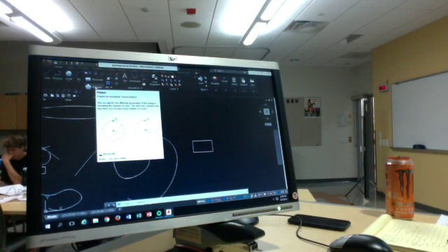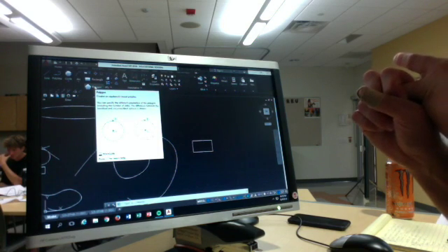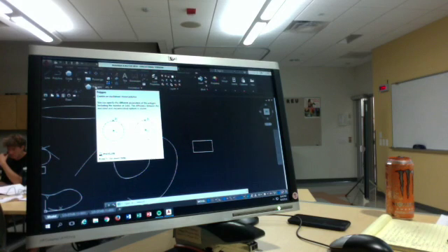You specify the center point, how many edges it has, and the radius of the circle, and it's going to be touching the circle with the points. Circumscribed about circle, you specify the center, the radius of the circle, and the number of edges, and the center point of each edge is going to be tangent to the circle.